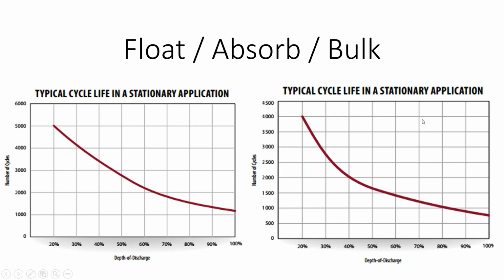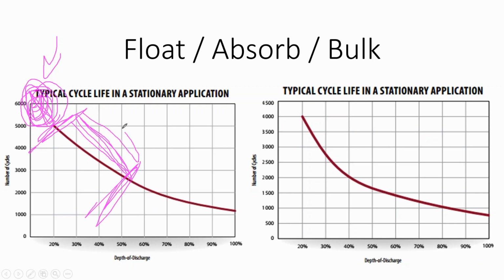So anyways, when we have our float stage, we don't really have to work. We're not really charging our battery. Any kind of cycling at that stage is not doing too much damage to the battery. Then we have our normal operating range in this absorb phase, and that's where you want the load coming out and then the solar array charging it back up. When you get past this inflection point and get into this bulk phase, that's when the most damage is occurring to the anode.